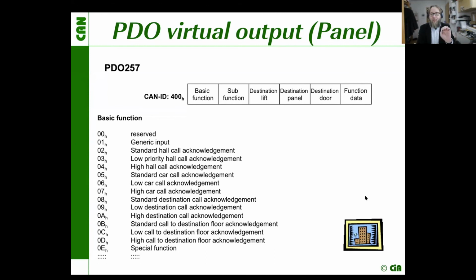to make it possible to do some kind of plug and play. Some kind of plug and play, because someone needs to define or tell the push button which type of push button it is, at which floor it is positioned, at which lift, what the call controller should do with the information. What does it mean if it's a priority call or not? What lights should go on?